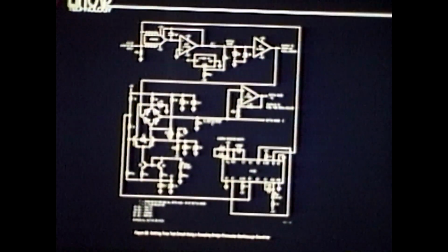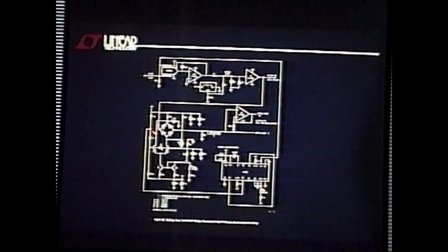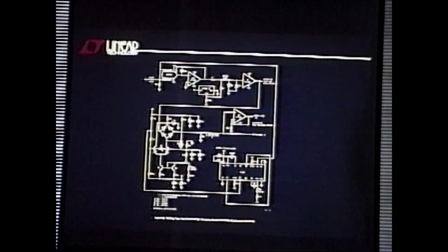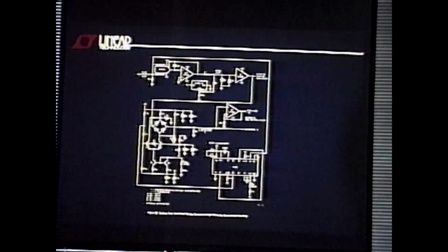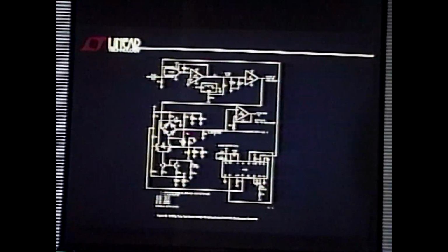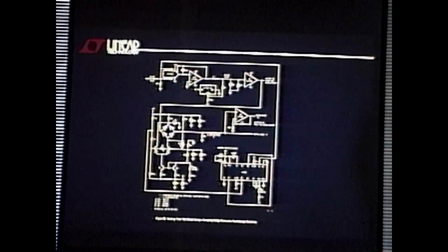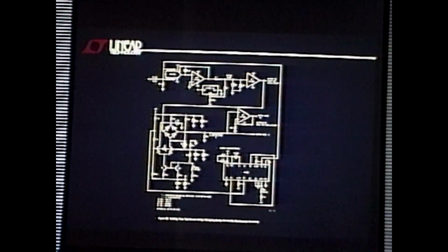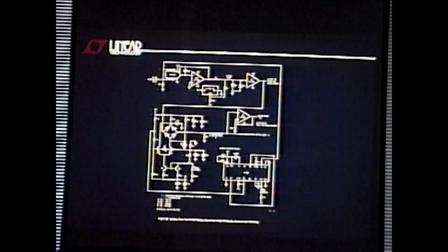Why do I use a bridge? Why don't I just use a FET switch here? Why do I go through all this bridge business? The reason is the gate-to-source capacitance in a FET will generate more waveform artifact here as I drive the gate. No matter how careful I am about the gate drive, you've got capacitance from gate to channel, and you're going to dump charge onto this line, which is probably going to be a larger amplitude signal than what you're trying to see. So you'll probably end up overdriving the scope anyway.